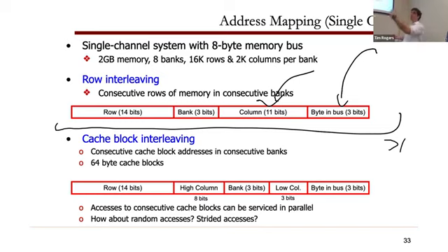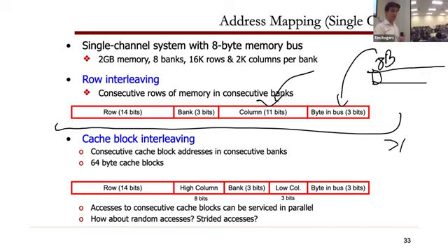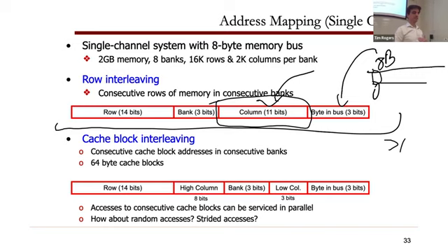So what this means is that the first 8 bytes are going to be here on a row. This is column, logical column 0 if I'm indexing it by 8. Then where are the next 8 bytes going to be if I put the next 11 bits as the column bits? Different row? Different column, right? So I'm going to use these 11 bits as my column index.